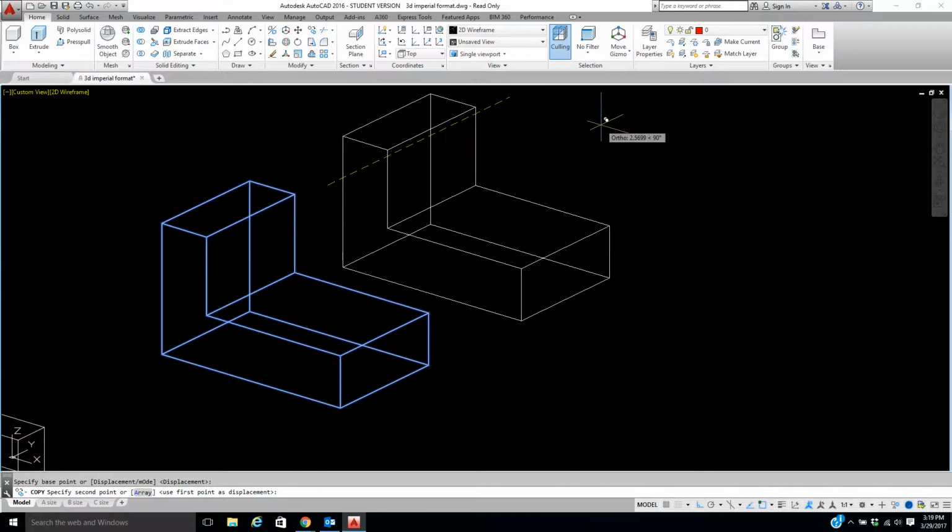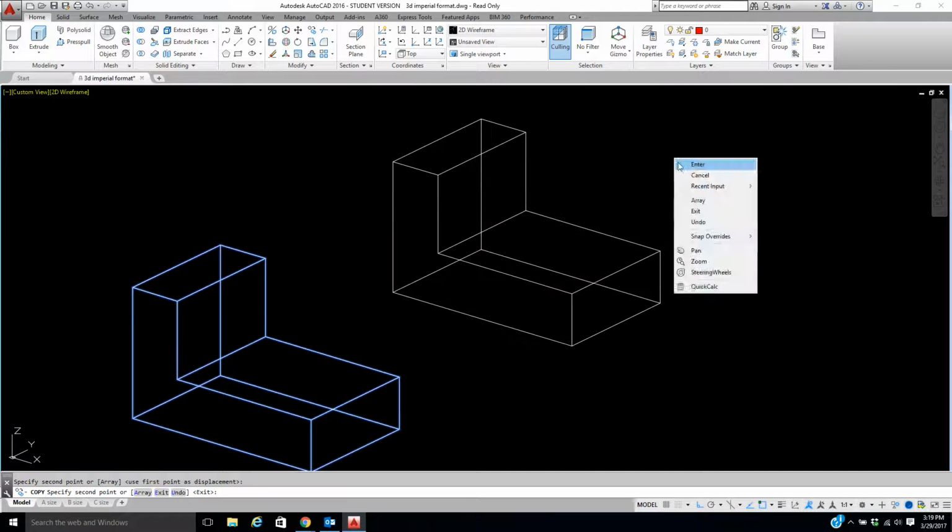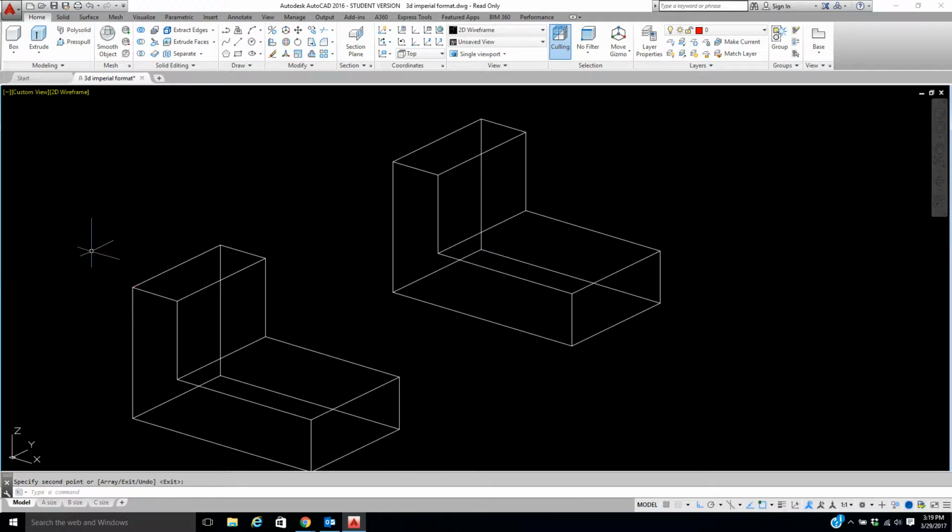All right, let's do this. Okay, so you see I drew that line right here. I drew it back 0.25 because that's where I know the hole starts. At this point, I can come over to box or rectangle. If I go to the box and pick right here, I can type in L for length.